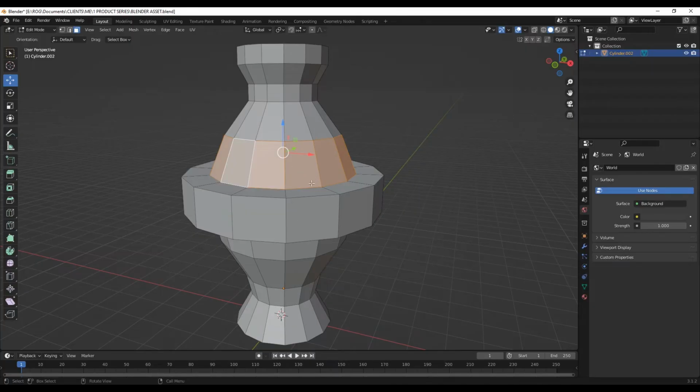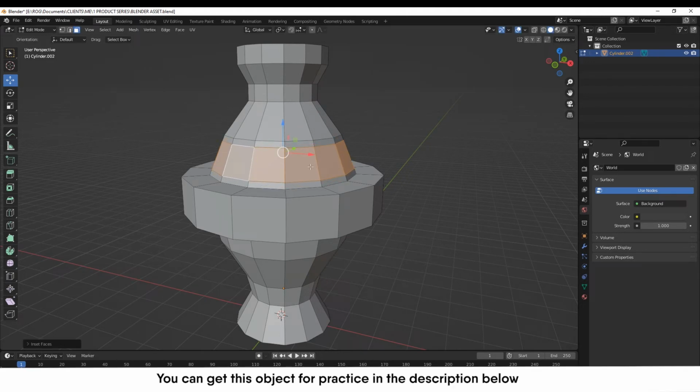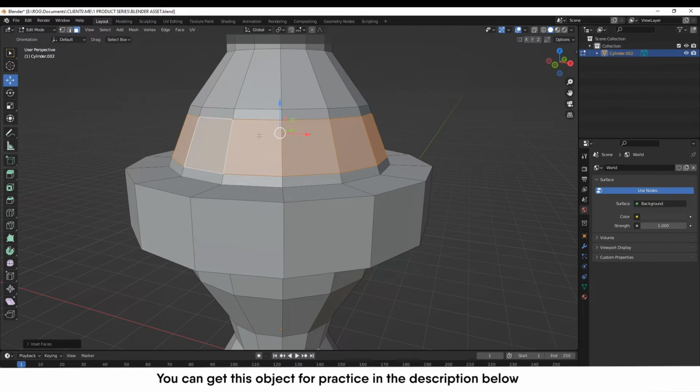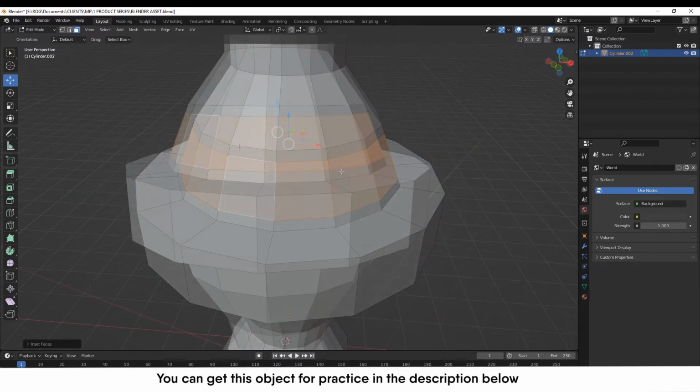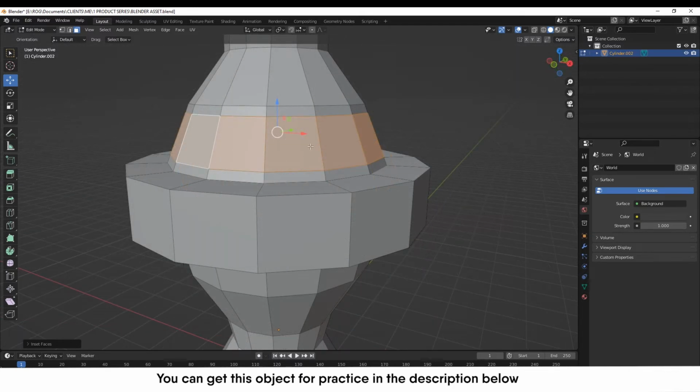Another modeling tool we can use when we select our faces this way is to extrude these faces or insert the faces. So to insert these faces here, just hit I on your keyboard. And then once you hit I, it will give you these dotted lines. And if you drag inwards, it will insert those faces. And so I can left click to place that selection. Note that once you insert a face, you automatically create an edge loop around those faces you've just inserted. So you see here, I have new loops, and then I can perform other actions with this loop selection here.